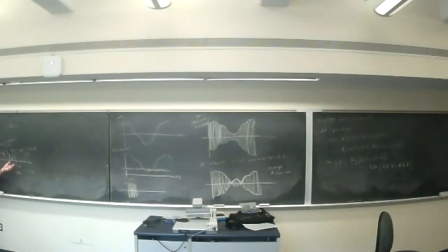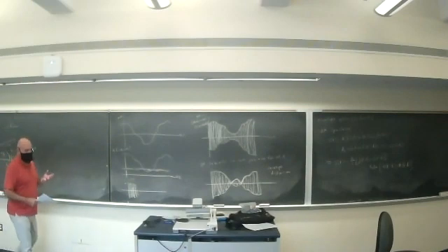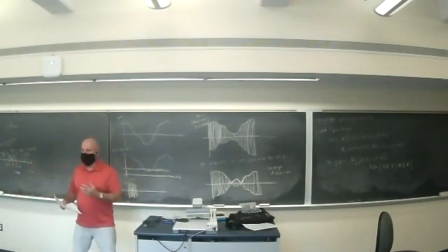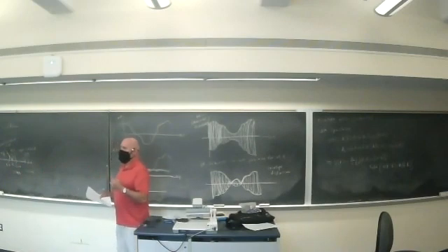They said, we're going to allow transmission up to about 5 kilohertz, so we have to space our stations 10 kilohertz apart. Okay. So again, inherently in AM, it's not good for music. Standard AM radio is not good for music because of that 10 kilohertz spacing. They only allow frequencies up to about 5 kilohertz. That's why most of AM now is talk radio.